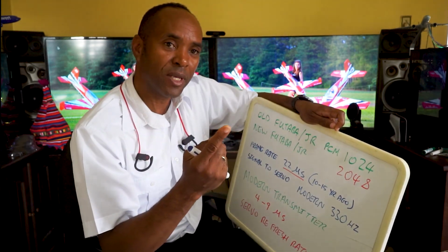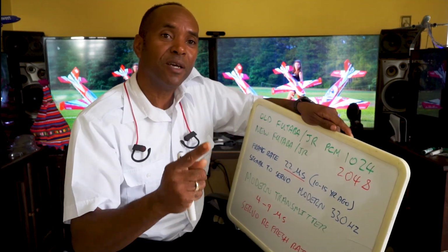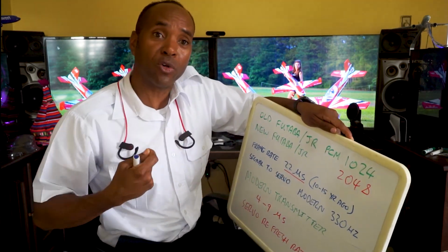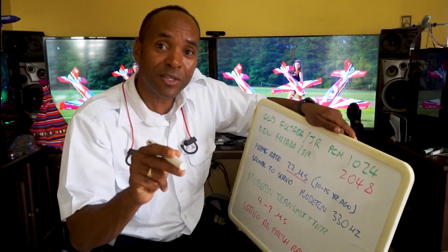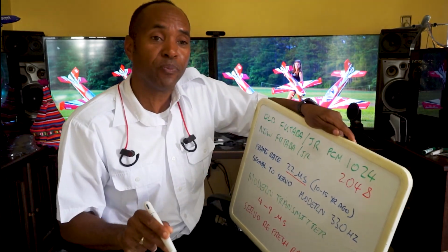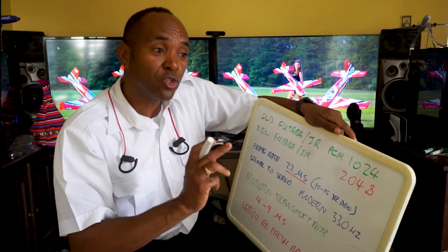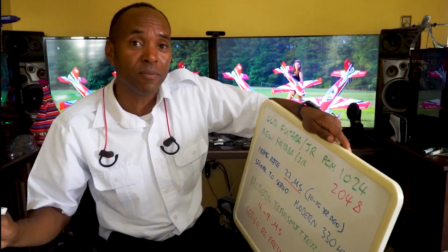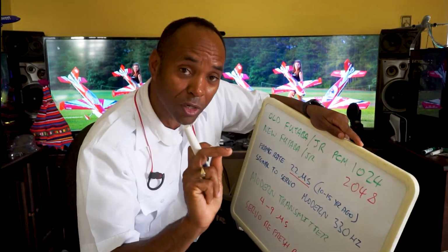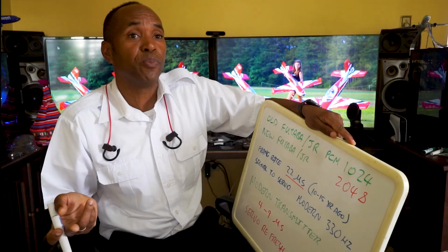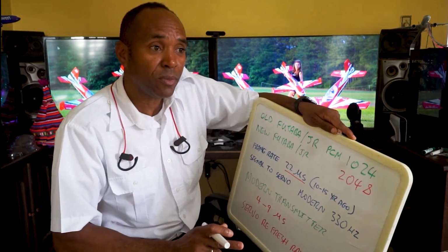That's S-bus capable. A modern servo can take an S-bus signal going in or coming out, to the point where you now have to program the servo and tell it which channel to respond to, regardless of which servo pin you put it in, right? If you program the servo to respond to channel 1, no matter which pin you put it in, that's what it's going to do. And it's not going to work any other way, according to the S-bus program.